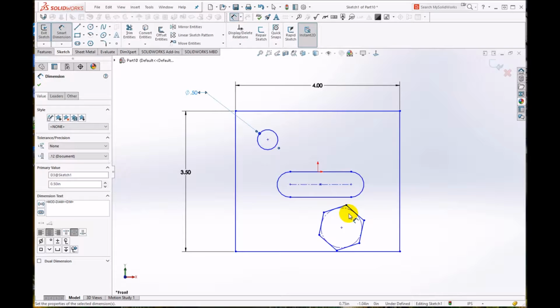This is a good moment to talk about datums. A datum is a reference edge, and we'll usually have a datum for each of the three reference axes, X, Y, and Z, for any given part. I'll declare that my left edge here is my horizontal datum. So everything horizontally will be dimensioned from there. Vertically, my datum will be my bottom edge. So in effect, what I'm declaring is that this lower left corner is my origin.